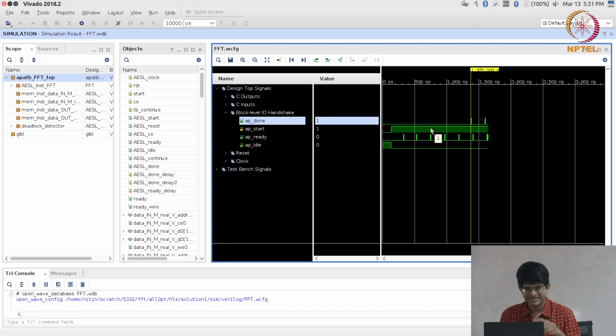Okay. So, the way that the test bench works is, because you had only given it one FFT call, it still puts it in a loop until it is able to at least measure the one done signal. Okay. So, if for whatever reason your Verilog code hangs and is not terminating, not generating a done signal, your simulation will go into an endless loop, right. So, there can be situations where you actually end up not crashing even, but just sitting there simulating endlessly. Okay. So, those are all things that you need to be aware of and catch if necessary. But this very clearly indicates the difference between latency and the pipeline initiation interval also.